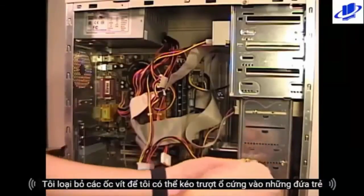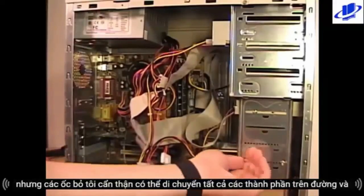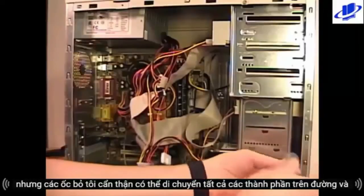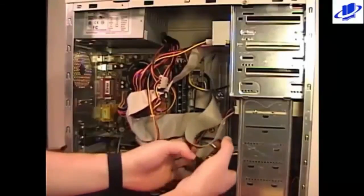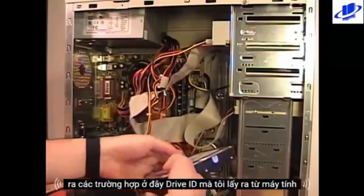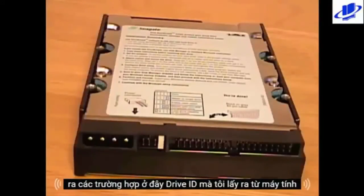I'll remove these screws so then I can slide the drive out of the case. With the screws removed, I can carefully move all the components out of the way and then slide the drive out of the case. Here's the IDE drive that I removed from the computer.